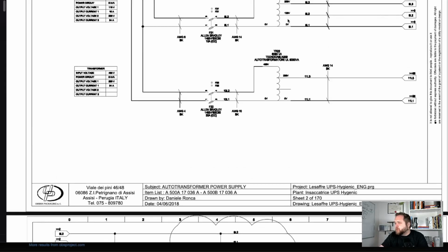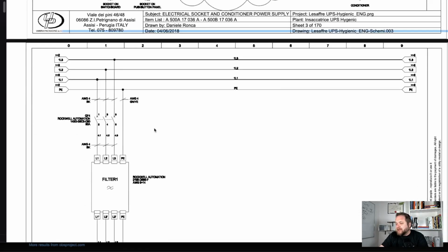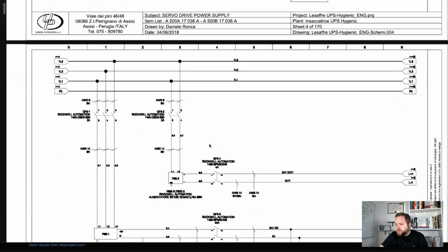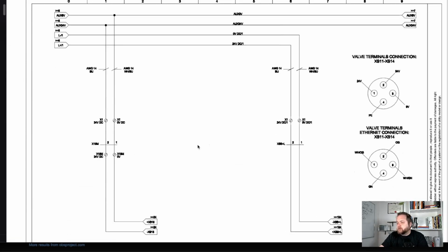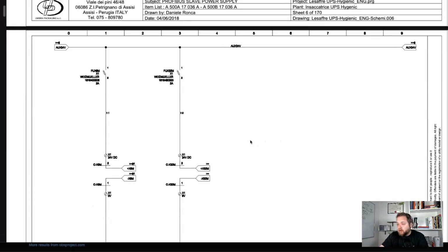So there's one that's going to be 110 or 120, and one that is 230. In this case, it's the 120 line. And as we continue to scroll past this, you'll see there's going to be a tap on the 3-phase filter side. So I'm assuming this is going to go to your VFDs or motors. Again, I'm not going to explain every single detail about the schematic. This is actually a very good attention to detail. So some of the terminals, and if you've worked enough with the Rockwell system of wiring some of those cables, are a very good addition to the prints, because it sets up a reminder for someone who's wiring a lot of those circuits.